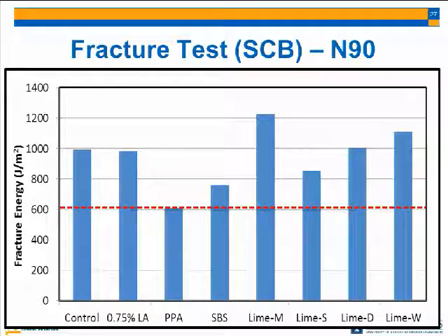So would you say most of the damage is coming from the moisture inside the aggregate? I do believe so myself. Look at it this way: when you get a pile of aggregate sitting there, all the quarries measure the moisture in the piles, and you get maybe 1% moisture, or sometimes even more, depending on what aggregate you're using. You heat it for 30 seconds, and what you have is a shock heat, and all the moisture either evaporates or goes inside the aggregate, correct? I mean, entropy here.